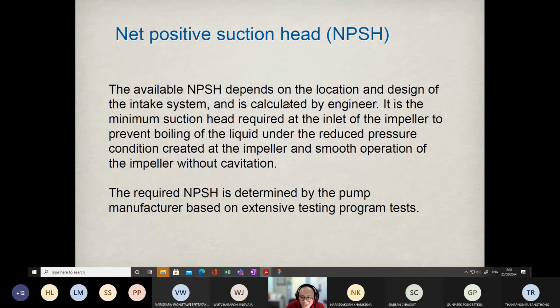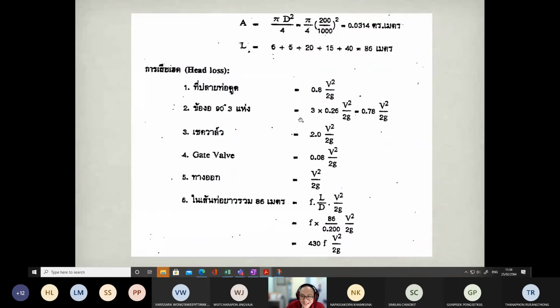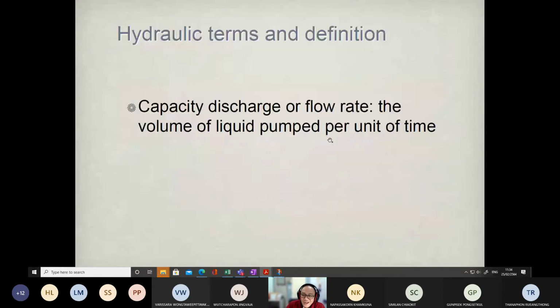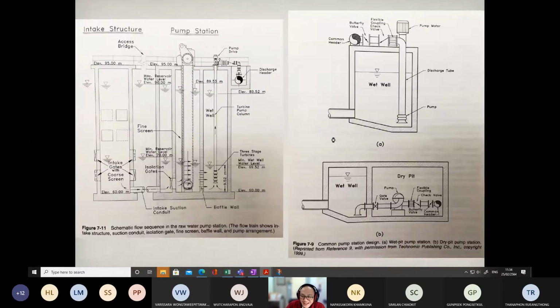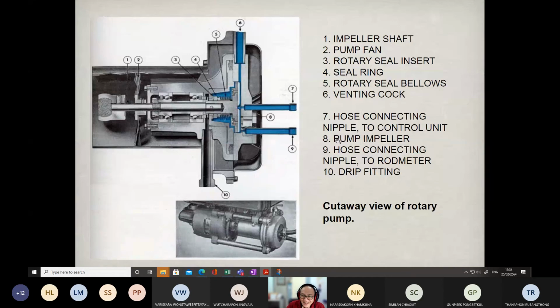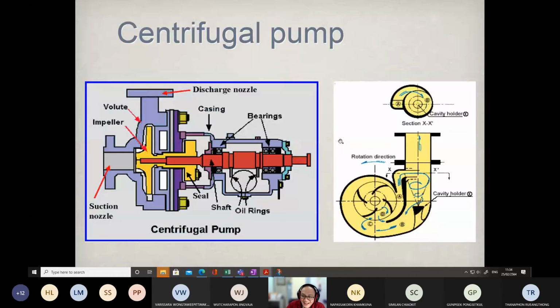You have to imagine the casing, with water entering the casing through the axial direction. Once the impellers rotate, the pressure increases near the wall of the casing, but at the center the pressure generally drops.